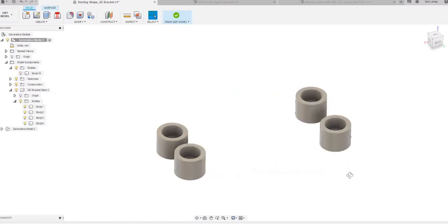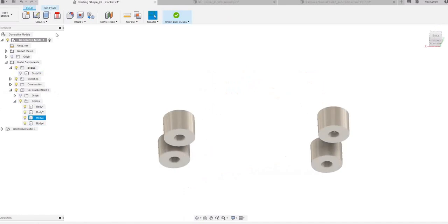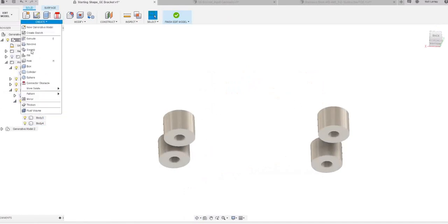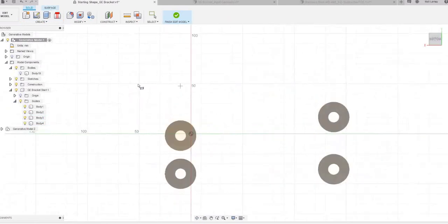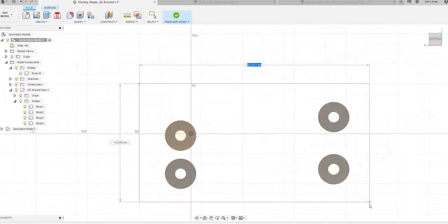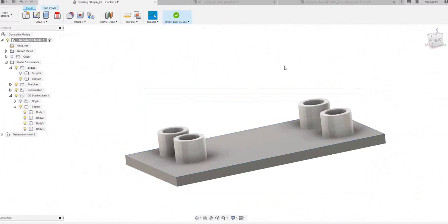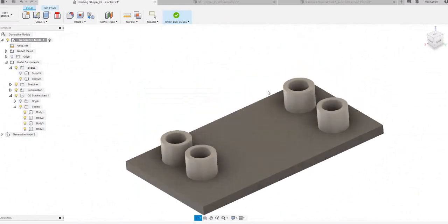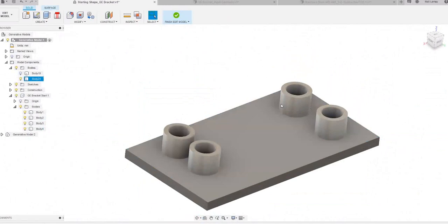So now I can go ahead and hide the initial geometry. And we also know that this bracket needs to attach to a plate, so we need to create that geometry ourselves. In this case, we can just select one of the faces, create a box, and drag that down each time, making sure it's a new solid so we can call it out effectively later. Now we have the plate that we can avoid at the bottom, and then the pins for the preserved geometries at the top.